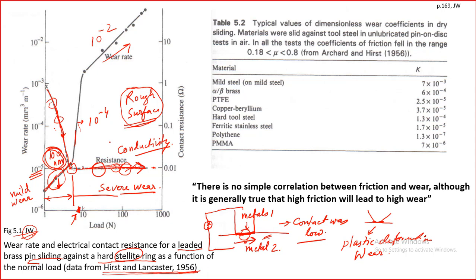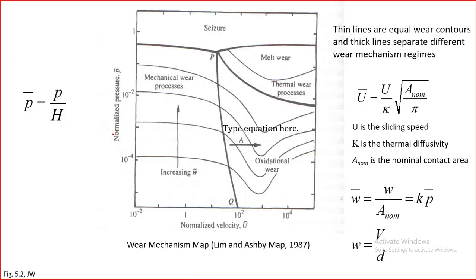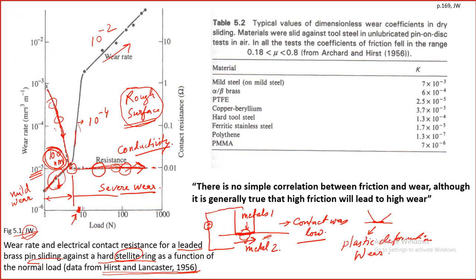Okay. And there will be large metallic wear debris particles. So wear debris particle size may be 0.01 millimeter in diameter. Low contact resistance, as we already discussed, the contact resistance is low. So this is a very good way of understanding the wear process. But there are many more ways that wear can take place, but this is one very initial way of understanding it.